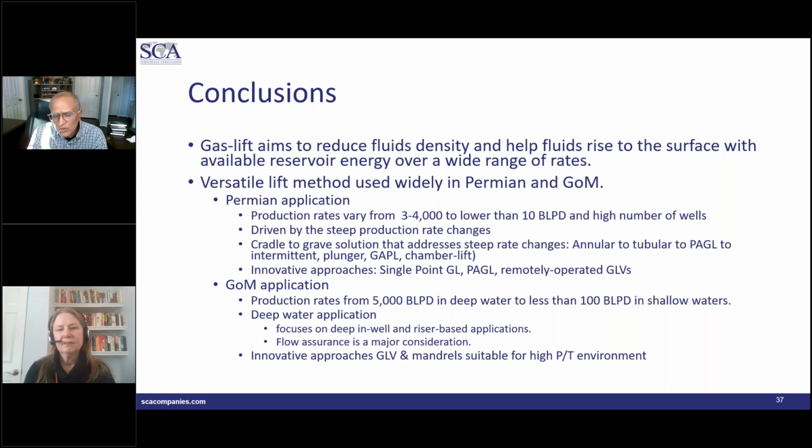Especially if you have a strong water drive aquifer, your formation gas quantity may go down, and in that case you may not have sufficient gas to meet your injection gas requirement as well as your sales requirement. As I was mentioning, I have seen some cases whereby the operator had to actually buy back some of the sales gas in order to inject it. Hope that answers the question.